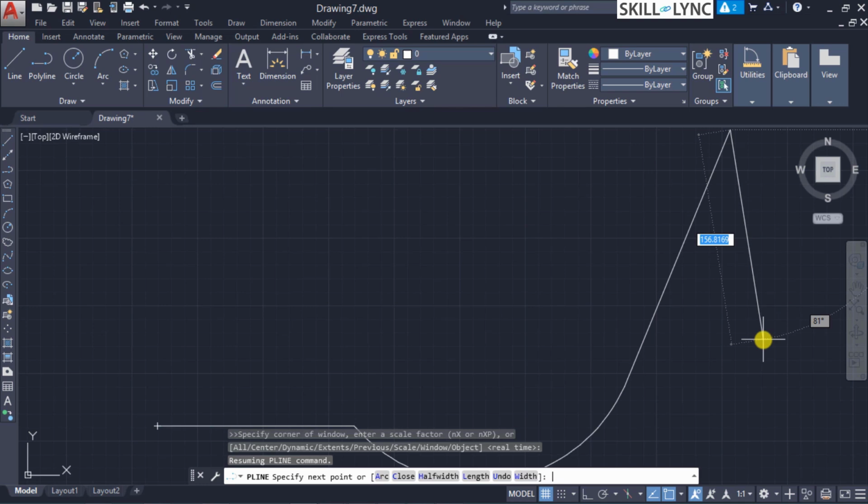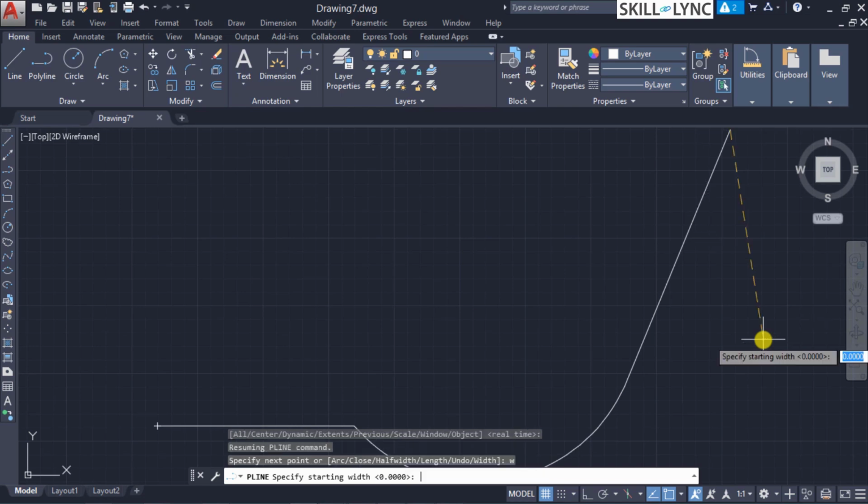and now let us continue one more line here. But before proceeding, let us try and change the width of this line by invoking the W command. Once it starts, it prompts for the width of the line. Suppose we want a line width of, say, 2 units, and it asks for the end width, that is, it asks for a start width and an end width.